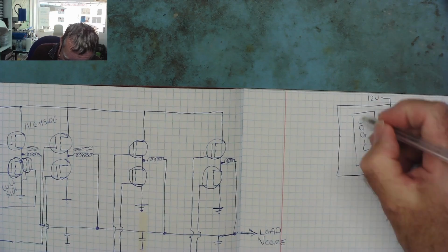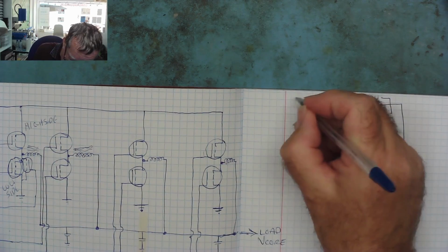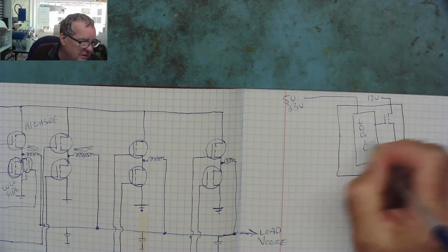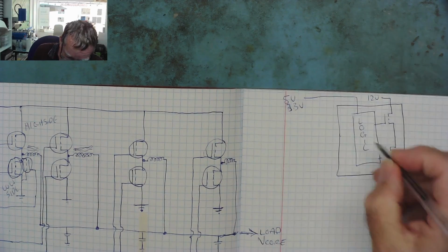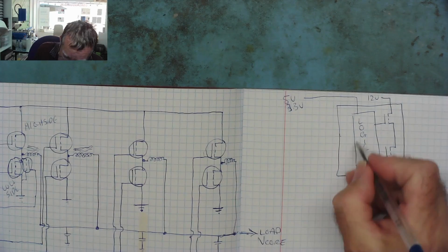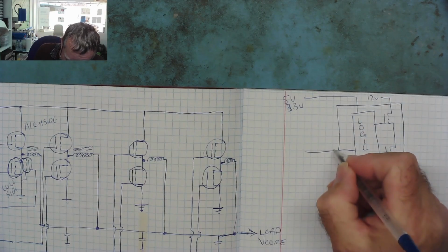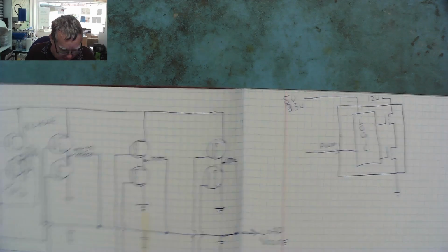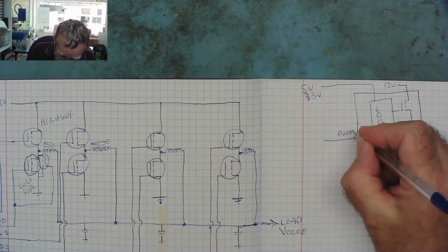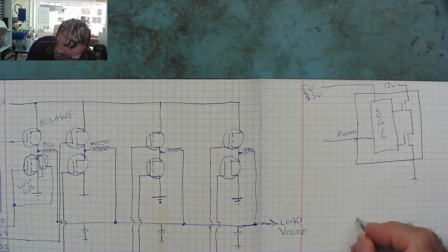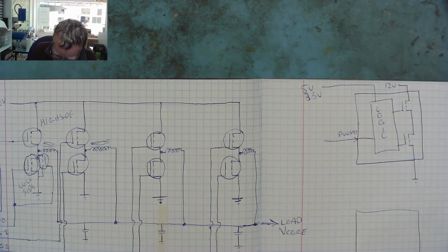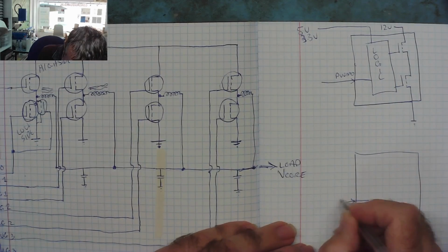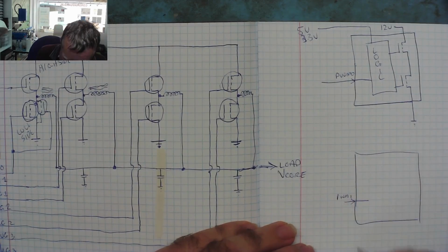This logic circuitry will have a power supply, often 5 volts or 3.3 volts, but it could be any supply that's on the board. It could be 12, but often it's 5 or 3.3, and the logic has coming into it PWM. So in the case of the first phase, PWM 0, and then we have another one of these driver chips, just the same thing, inside exactly the same as this one, and coming into here will be PWM 1 and 2 and 3.